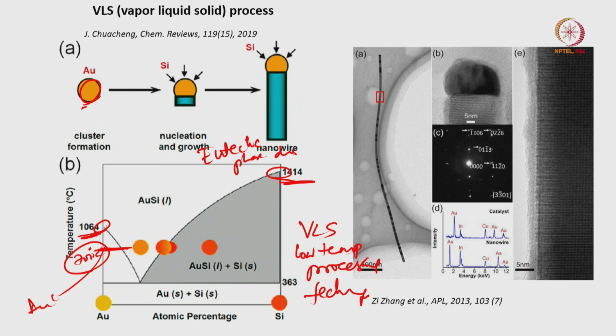And in the eutectic phase diagram, where are the pure alpha and beta phases? The pure alpha and beta phases are almost here, right. So this is pure gold, because gold does not like combining with silicon in the solid phase, and this is pure silicon, and same thing with silicon, silicon also does not like combining with gold, right. So this is pure silicon, this is like my beta phase, this is pure gold, this is like my alpha phase, okay.